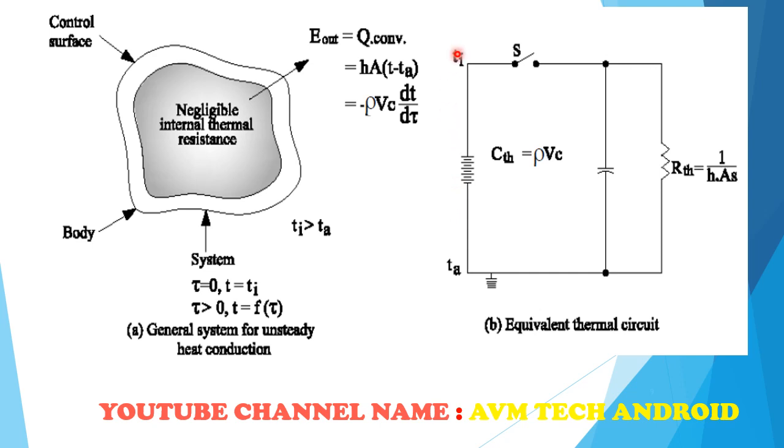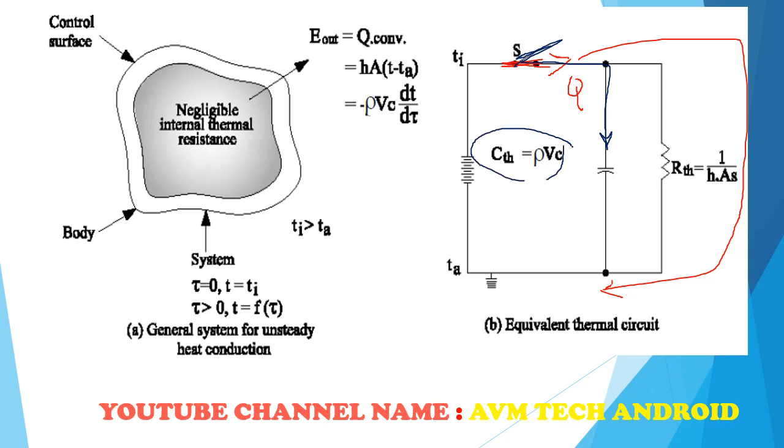Because of this temperature difference between Ti and Ta, the heat will flow through this system, and that will flow through this path when switch S is closed. When switch S is open, all the heat will flow into this capacitor, and that will be stored in this Cth, that is the thermal capacitance.